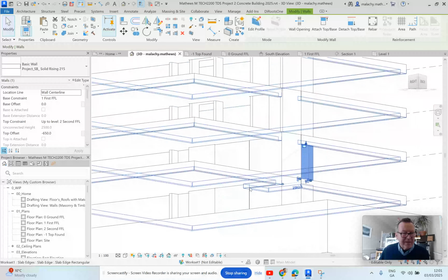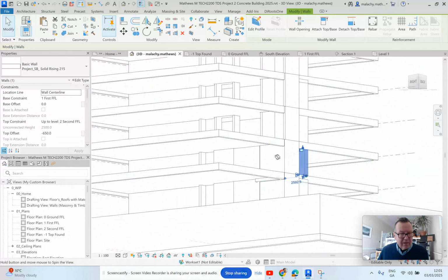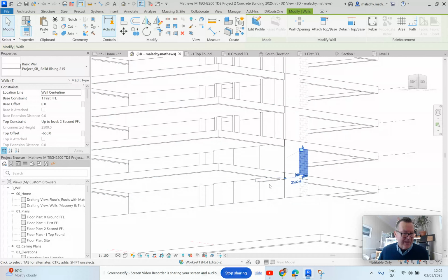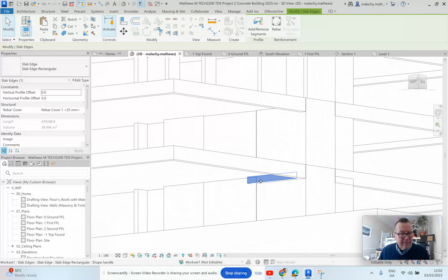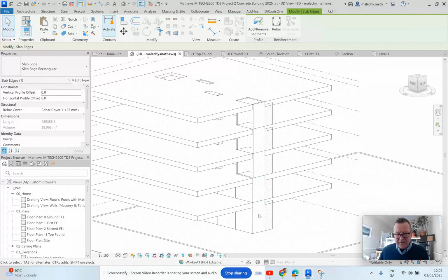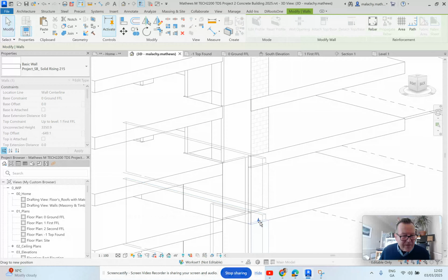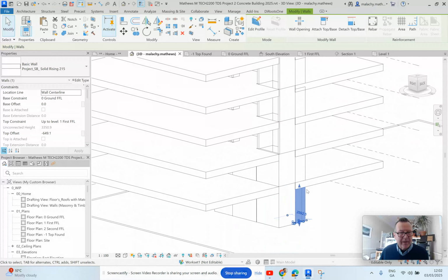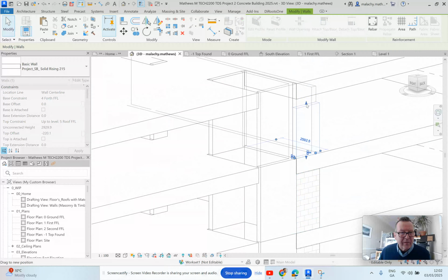yeah, you can see that the slab thickening has gone around the corner with that one. That's when I did the tab, and it found the perimeter the whole way around. Because that slab is going to sit on that concrete there, it's probably actually not really necessary, to be honest with you. So advantages and disadvantages of doing the perimeters around, nicely illustrated there. Okay, and it's best to just do all this kind of tidying up as you go along. So go below, then above.